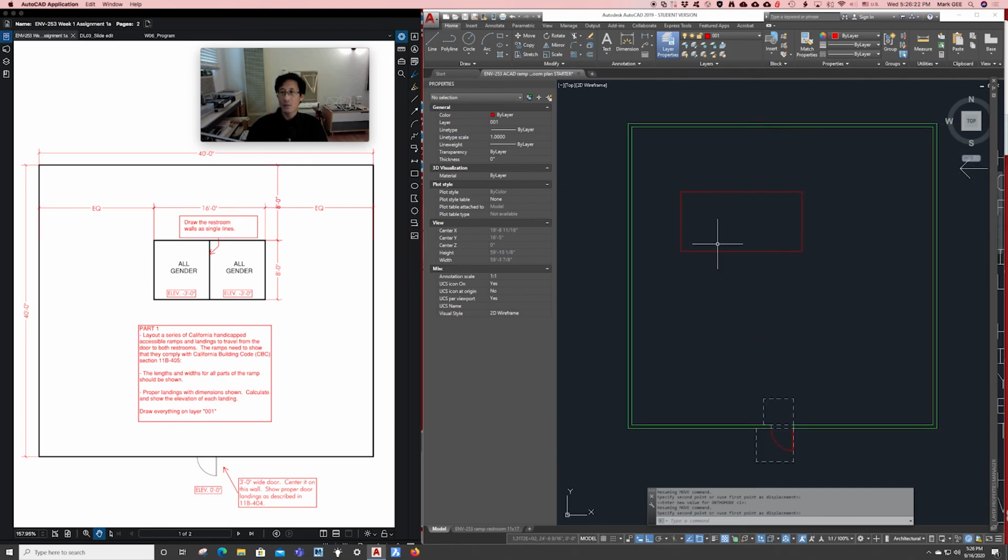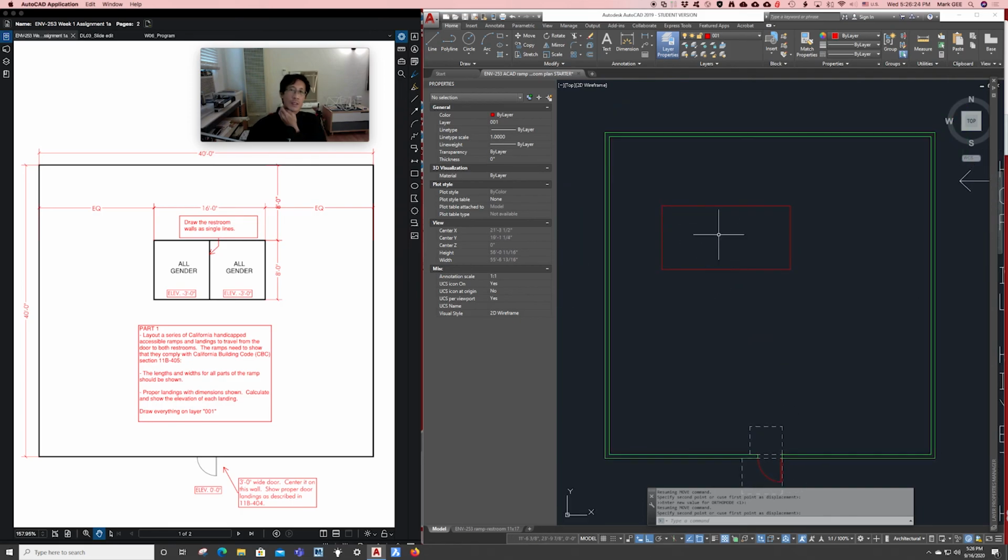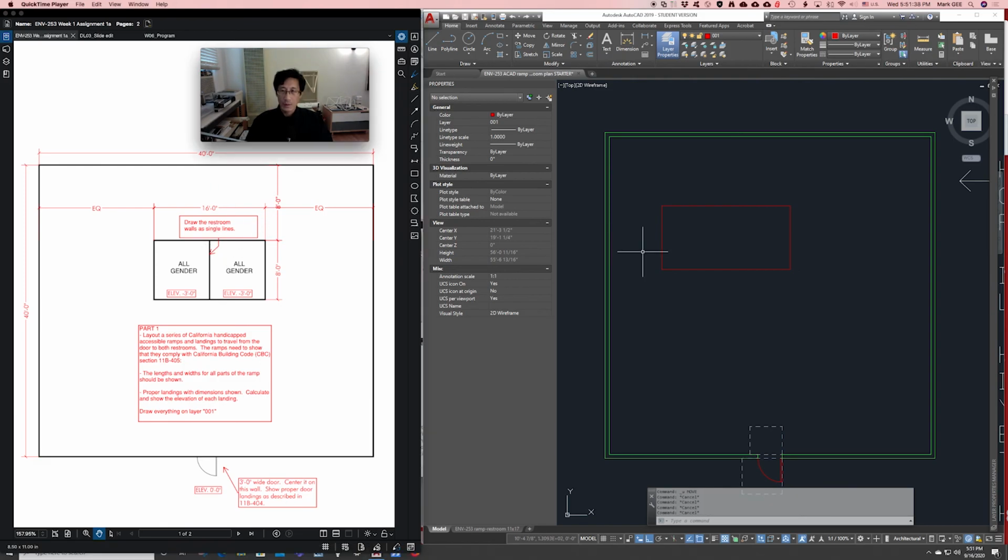Now let's zoom in here a little bit. How do we place this box where we want it to go? Well, I look at the instructions, and the location where it needs to go is equally spaced from the side walls. So basically it's at the midpoint of this whole space left to right, and it's 8 feet off the back wall. In AutoCAD, it is always more accurate and more precise to draw graphically than by entering numbers and coordinates into the keyboard.